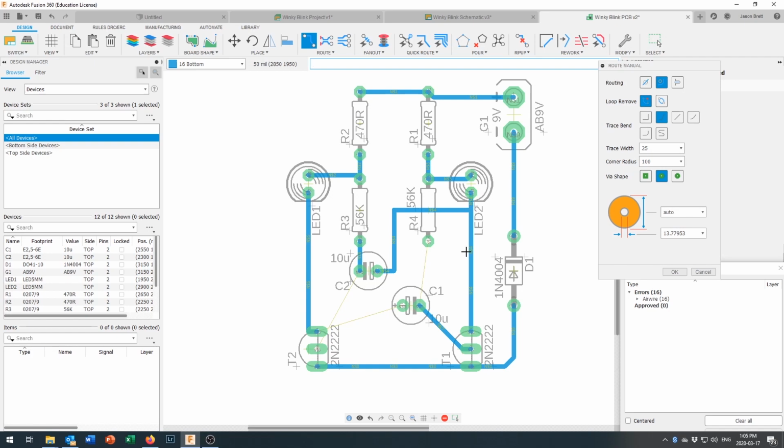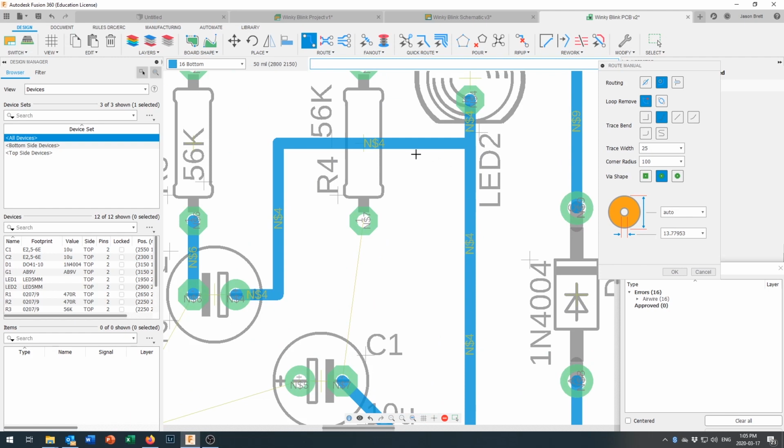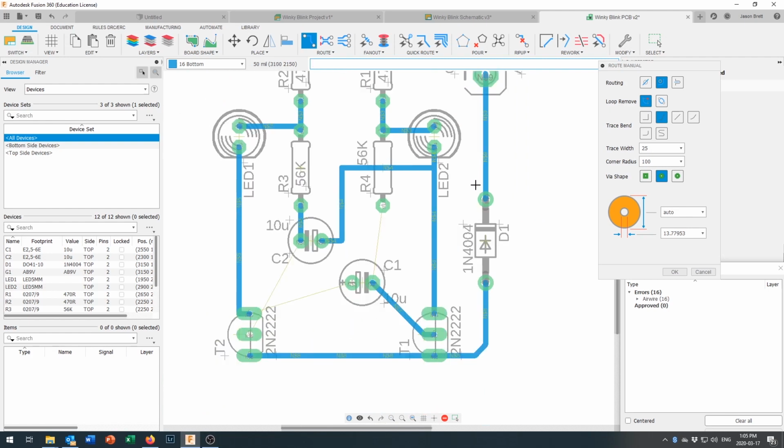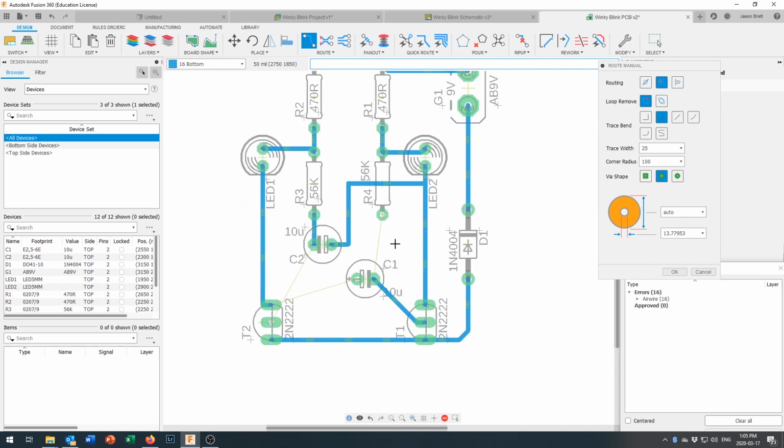And that's all connected. And when we look in here, it says net 4, and everything on here is labeled net 4. Everything over here is labeled net 9, and everything in here is net 8. We can change the names of the nets later on. That's a very useful thing to do when you have more complex boards. But by doing a couple clever things like that, that makes that a little easier to do.